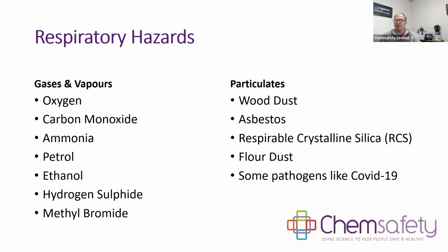And in terms of particulates, they can be in many different forms. So we've got our dusts or our fibers like asbestos. They can also be fumes like welding fume or mist from certain aerosols. So if you've got an aerated bath that you're using, that can generate a mist, whether it be acid mist or something along those lines. So they can be technically liquid or solid particles in different sizes.